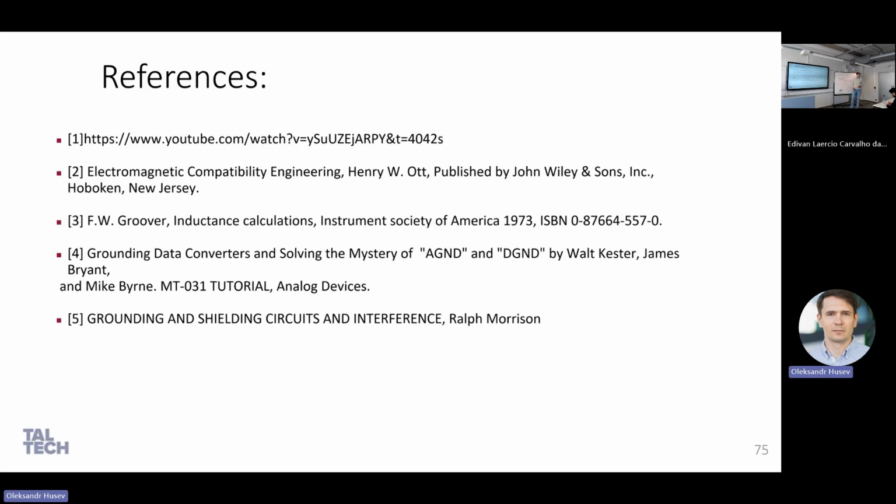If you have ZVS, I promise you, we can design a PCB and you will have this transient. We did it several times and you will put extra capacitance just by your PCB without any extra components. But you have ZVS, it will discharge, it's not harmful. It will not add any losses. But if you have hard switching, I would keep a little bit of this instead of adding extra losses, because this will add extra oscillation. But usually if it's like 350 V and you have 600 volt transistors, this is definitely enough.